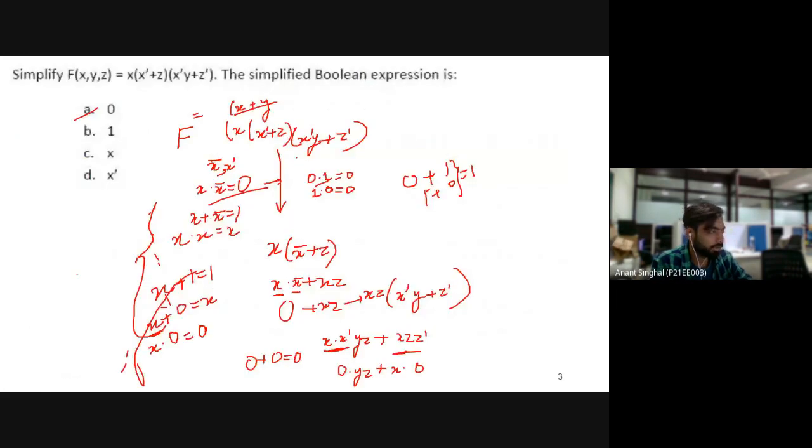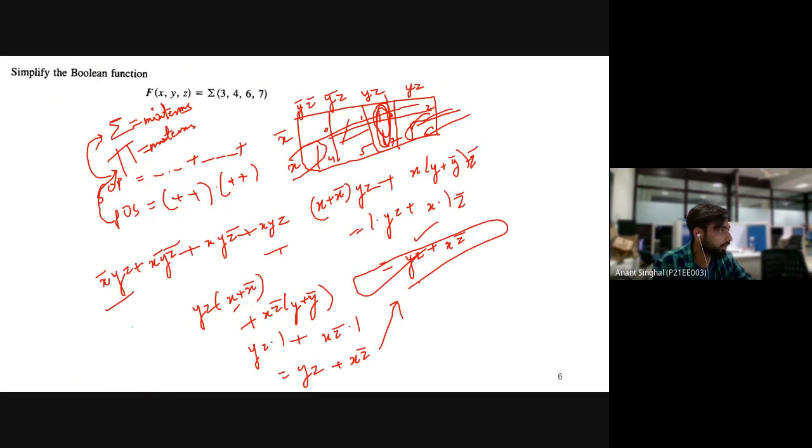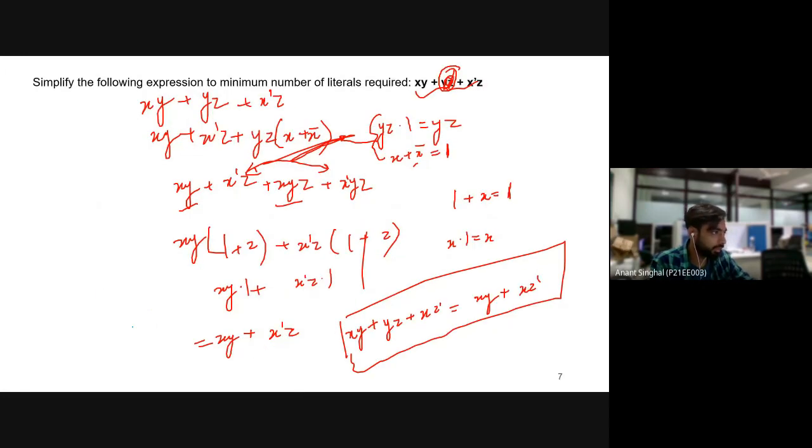So this was the basic question of Boolean algebra. Here we read about the basic axioms. Okay, wait. Here we covered these axioms and tried to minimize this expression. Then again a basic Boolean expression minimization question. This was one of the K-map questions, and I tried to solve it using both methods, since some of you are not aware of K-maps till now. Then this is an important theorem, that there are redundant terms in K-maps that we need to remove, and we have proved how we can remove them using basic Boolean minimization.